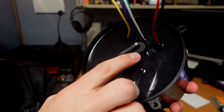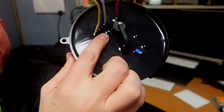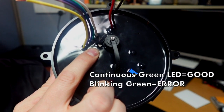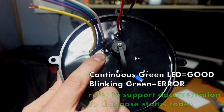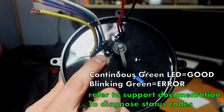And then up here next to the USB port, there's a small LED. If the unit is operating normally, you'll see the indicator glow a continuous green light. If it's blinking, there's an error. It'll blink according to the 2-digit status codes, and the exact error can be found in the support documentation.